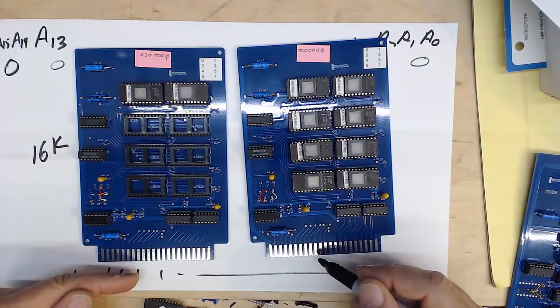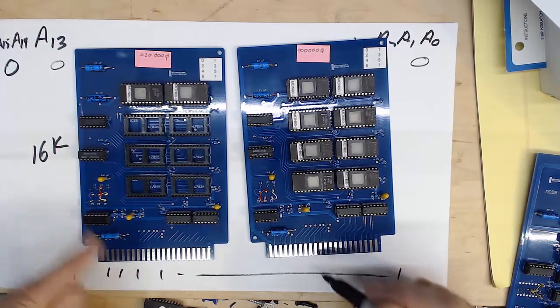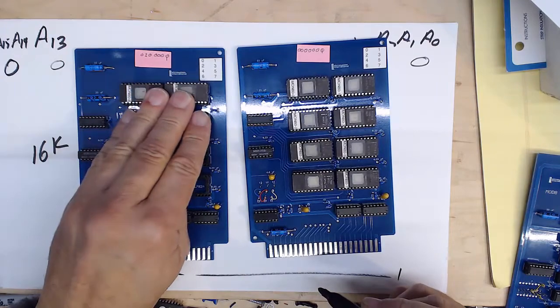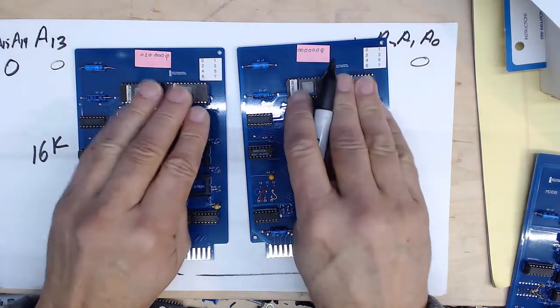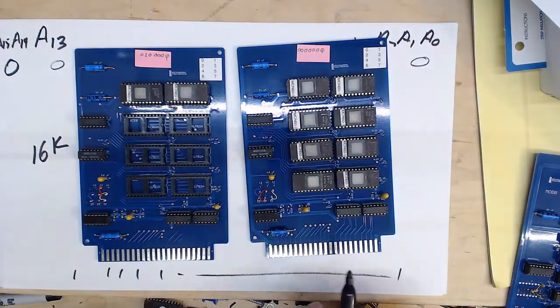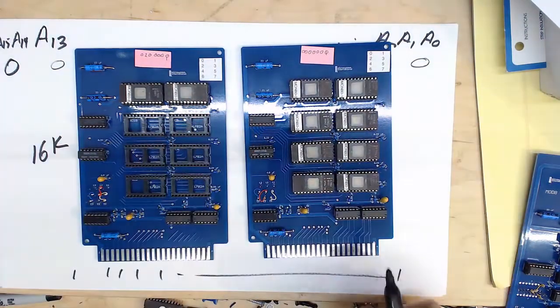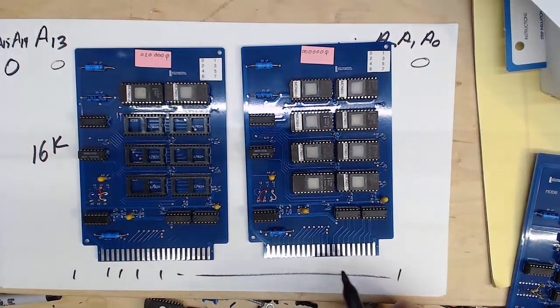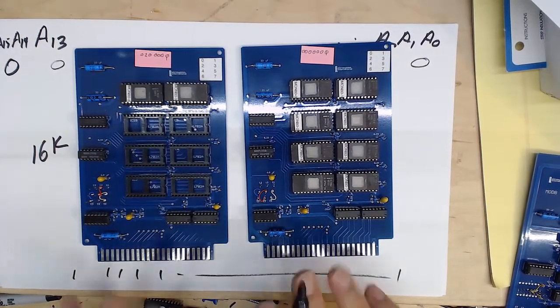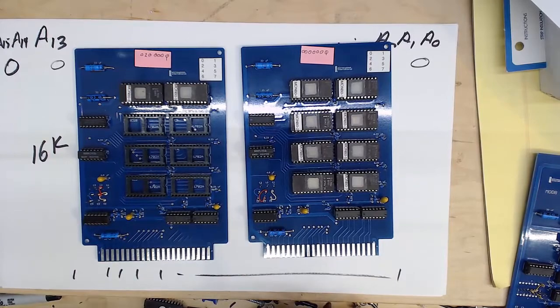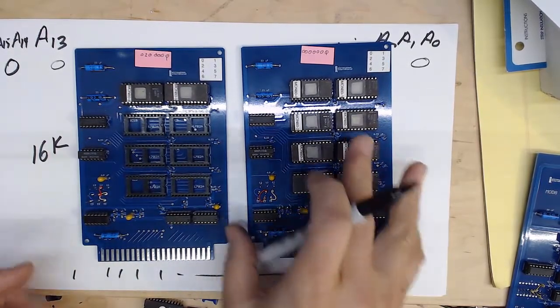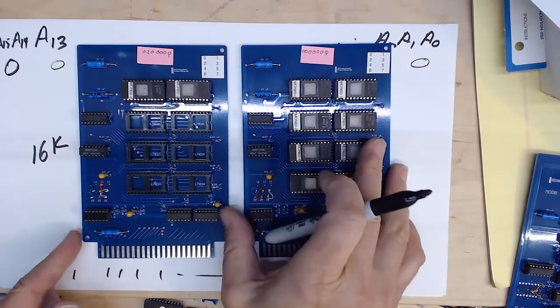If that information happened to match, there probably wouldn't be much of a problem. But if that information is different, let's say it's logic 1 from these and logic 0 from these, now we have a bus contention situation where these guys are trying to drive the bus high, these guys are trying to drive the bus low, and they can both go into an overcurrent situation, particularly the ones that are trying to drive it high. So it's important when we're mapping our memory out that we make sure we don't have any overlaps.